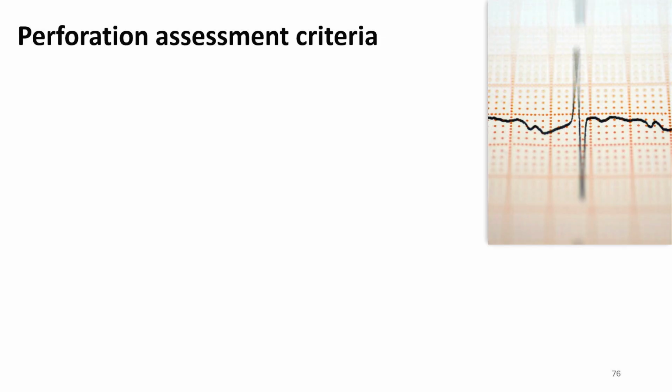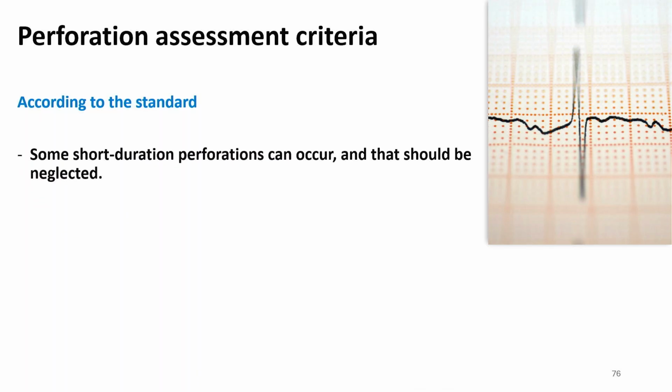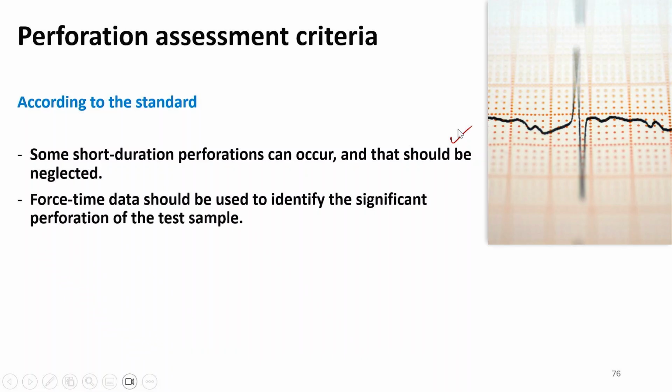Now, the perforation assessment criteria according to the standard. Some short duration perforation can occur, that should be neglected. The perforation should be of long duration. Force-time data should be used to identify significant perforation of the test sample.